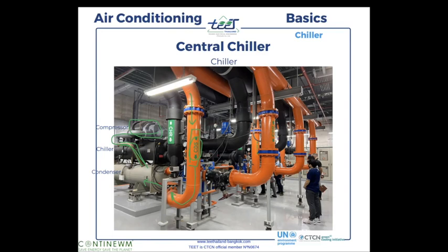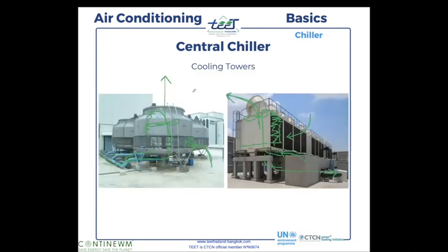And this one goes up to about this level, and at this level, after removing the heat from the compressed gas from the compressor, the water from the condenser of the chiller goes up here. And here you have CDR, condensing water return: condensing water supply, condensing water return, and this line goes back to the cooling tower. So this comes to the cooling tower, the principle that I explained before in the slide. You have the air, the water arriving and the water going back.